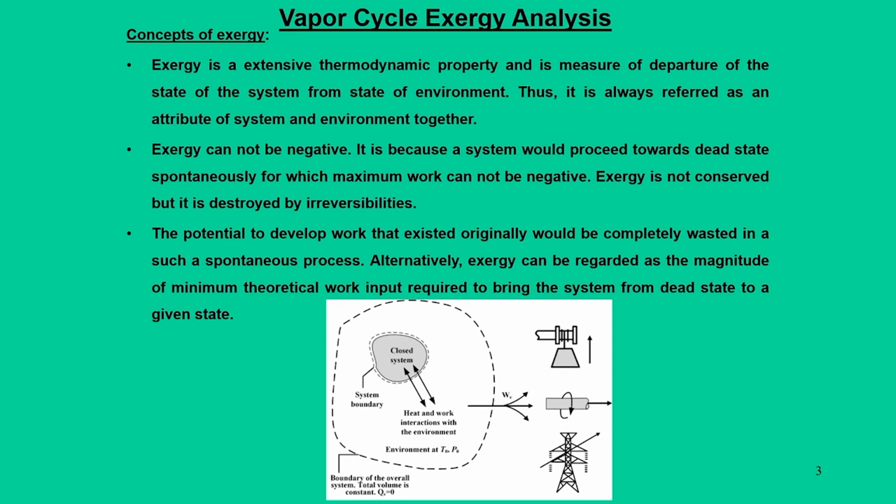When you say energy in thermodynamic viewpoint, we say it is available in the form of heat or work, and second law analysis says that heat cannot be completely converted to work, which means there is a certain potential that heat can be converted to work to a certain extent.